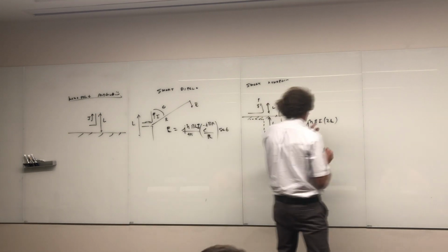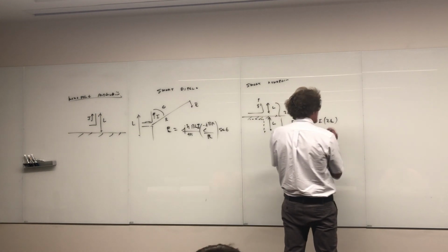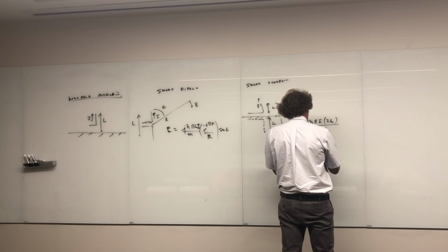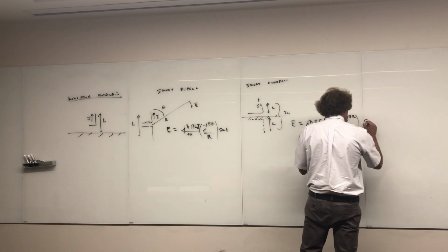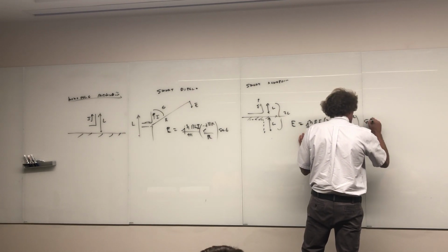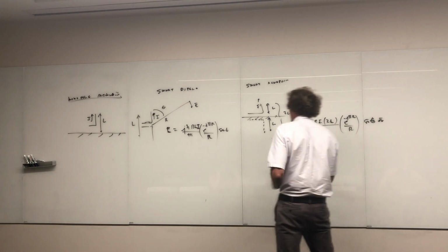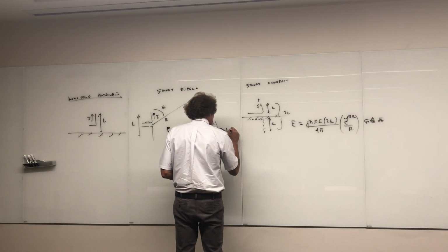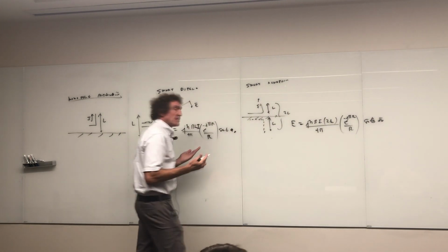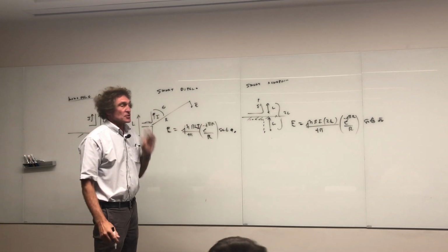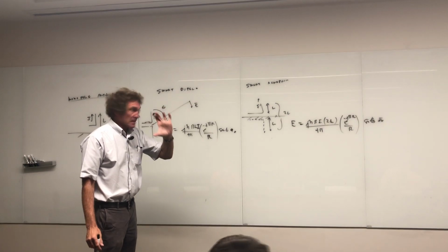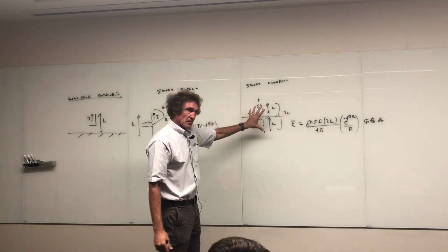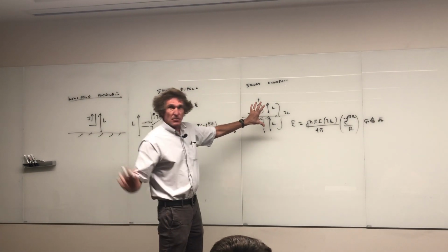It's j eta beta I times 2L over 4 pi, and then it's e to the minus j beta r over r, and still the sine of theta variation. It's in the a phi direction. They're both in the a phi direction. The only difference in the E fields from either one is that it has a distance of 2L. If the effective length of the monopole is L, the length with the image would be 2L. Do you follow me? All right, that's the only difference.